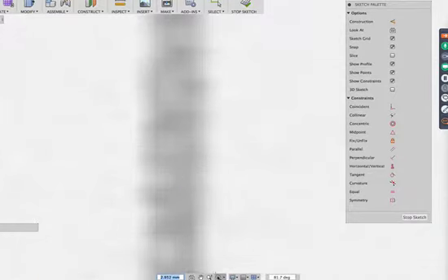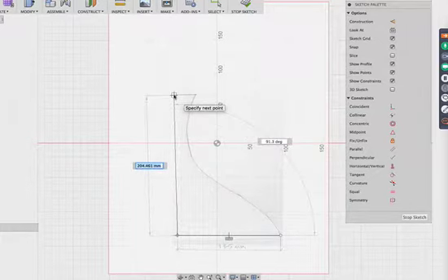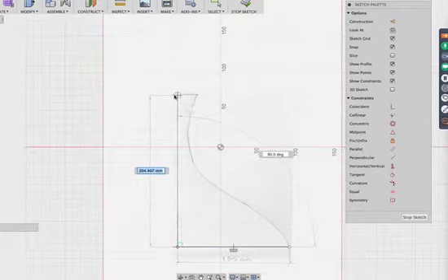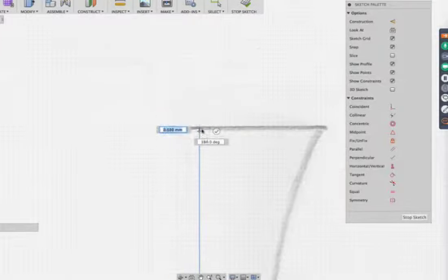Now I can right click and go repeat fit, which I don't really want to do. You can do press pull, which is kind of annoying actually. So I'm going to hit L for line. Click on that one. I want to make sure those match because it's important that all the lines have to connect. Let me zoom to fit. Let me just put it right up there. This is at 91. There we go. Here's 90 degrees. Boom, I'm set there. I'm going to move this up a little bit.